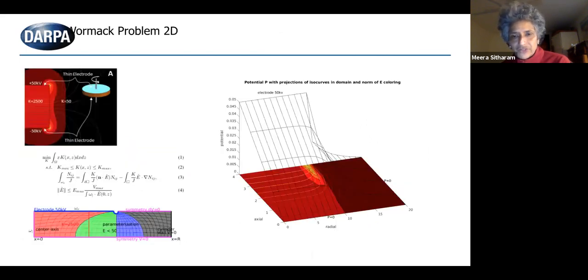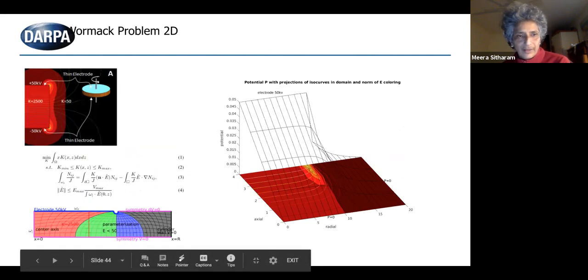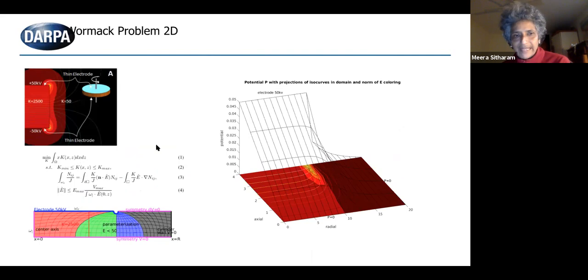We also did an electrostatic calculation. If you analyze it, the electrostatics and mechanostatics, what we know as stresses, are very similar. So using that, we were able to solve something about a capacitor, optimizing the structure of the capacitor, the dielectric constant of the capacitor, how it should be distributed so that there's no breakdown, so that the maximum electrical stress is minimized.